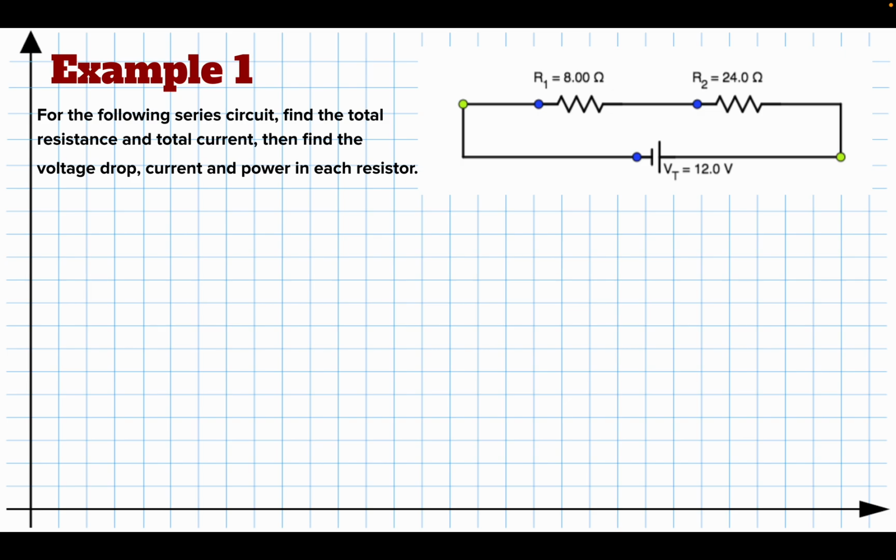So let's solve an example with this idea of series circuits. Here's the problem we're going to solve. I've got a voltage of 12 volts. It is causing charges to flow around the circuit. They lose some energy here, then they flow to this resistor and lose some energy, and then they get back to the battery. So if I start with 12 volts of energy, sooner or later I've got to lose 12. And I also know the currents are the same.